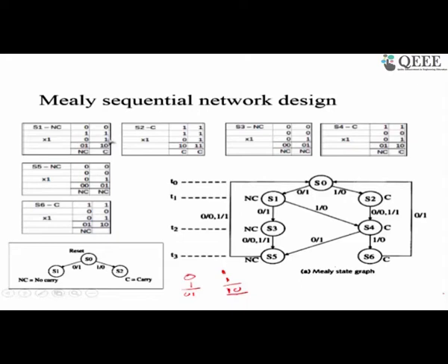The bit can be 0 or 1, but we know for sure that 1 needs to be added for XS3 conversion, and because there is no carry, there is 0 0. So we will see that for this case, on adding these 3 bits you get a 1 and 0. So we should go to a state where on getting the input of 0 we output a 1 and go to a no carry state.